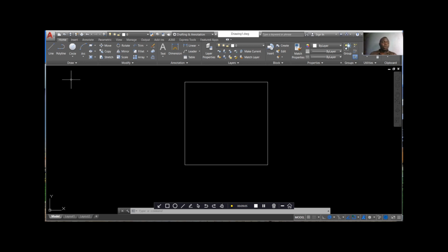Okay, so as you can see, this is just a box. It's the outer lines that I've done, or the outer boundaries of the room. Now, obviously, we shall be having a wall. So how to draw a wall now? I'm then going to also use offset. See, the offset function will make you enjoy using it.